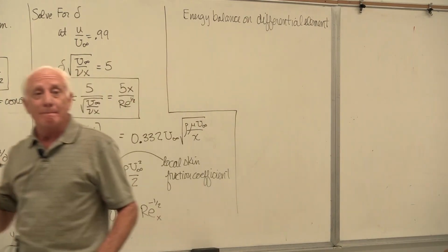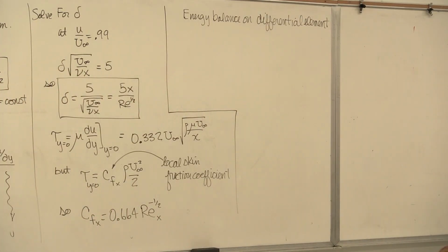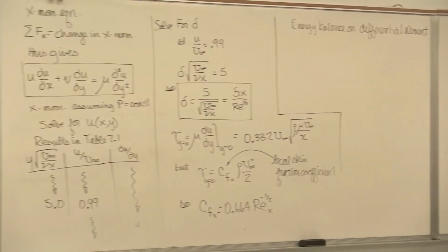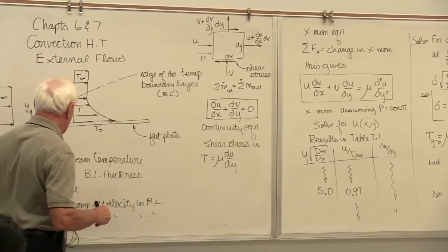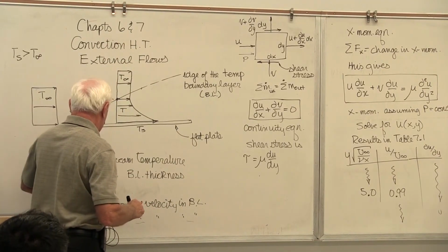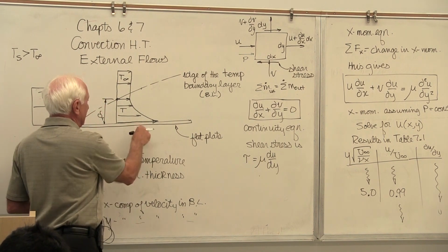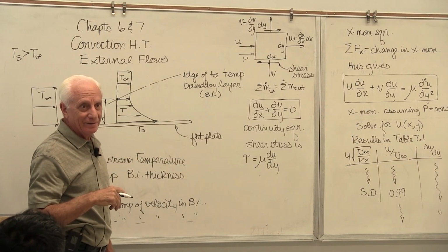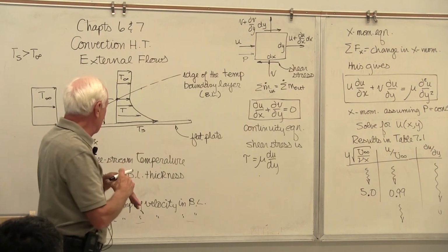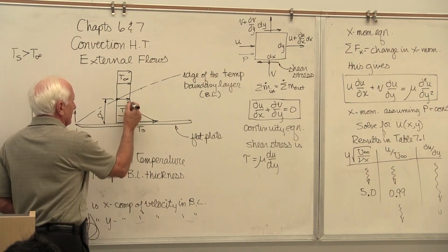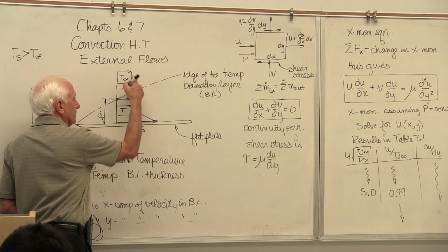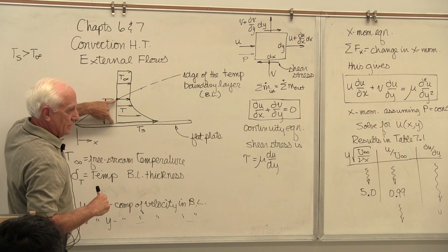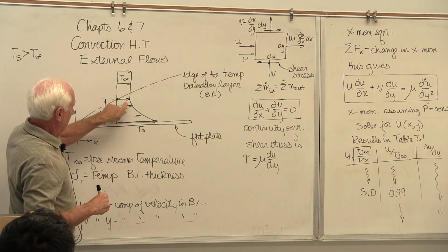That's still going to be U equals U, the 0.99. Yeah, it's going to be a temperature difference. T minus TS divided by T infinity minus TS is 0.99. So it's a temperature difference, 0.99. This point here is where the temperature is 0.99 of this total difference. If this difference is 100 degrees, you're within 1 degree right there.